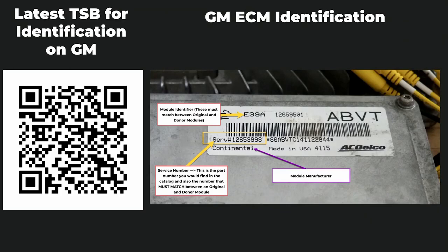There are also situations where the software from the vehicle manufacturer may be broken and you may not be able to program a brand new module to the vehicle. So in those situations, again, we may need access to cloning technology in order to keep the vehicle on the road in service.